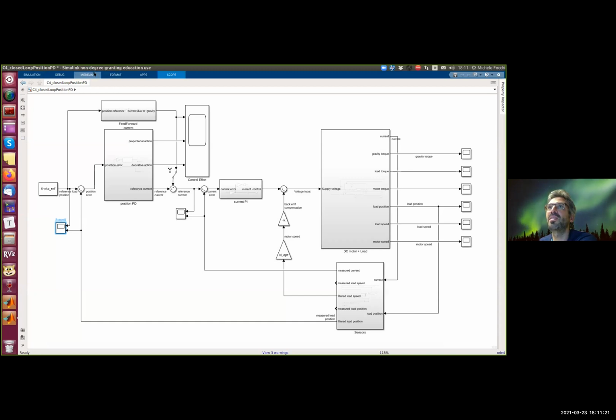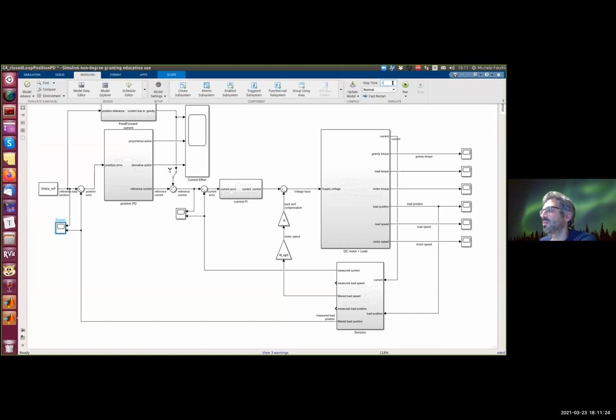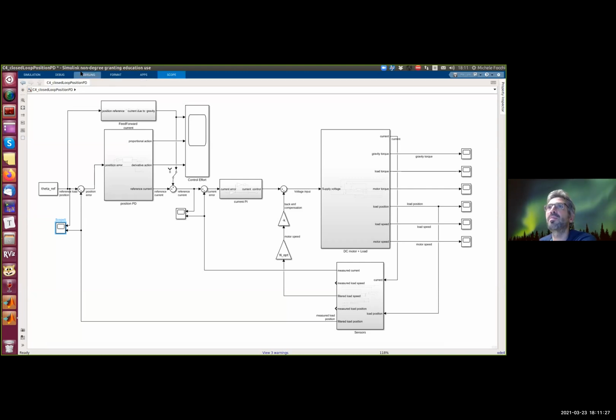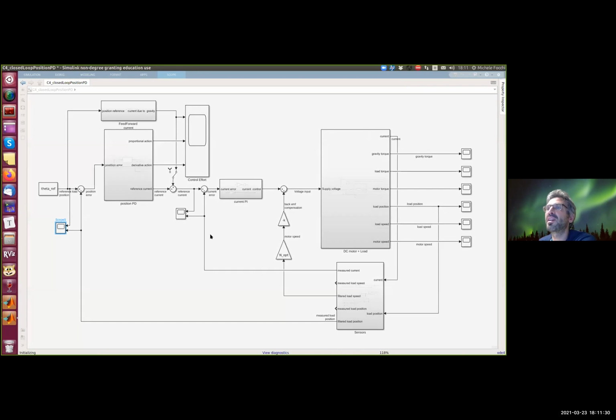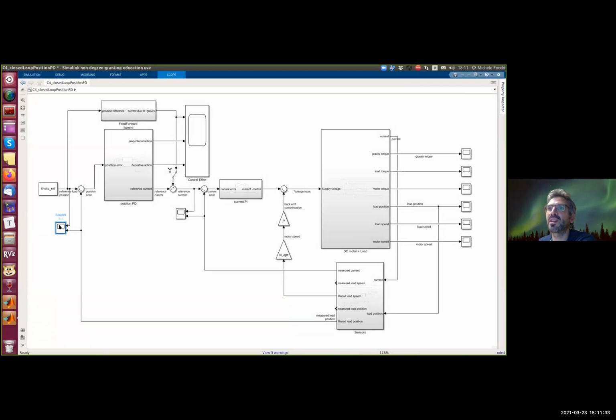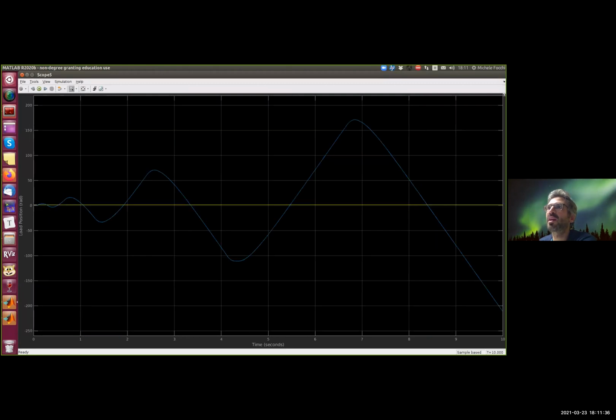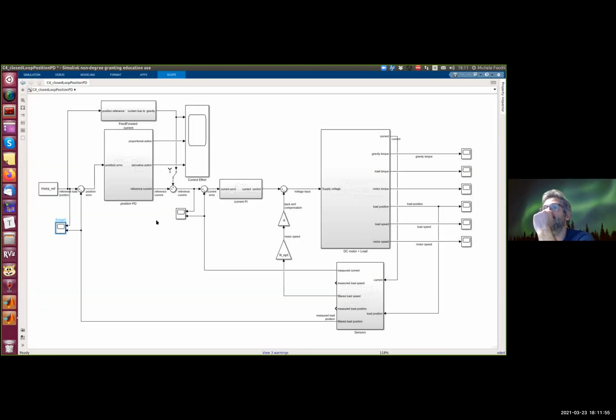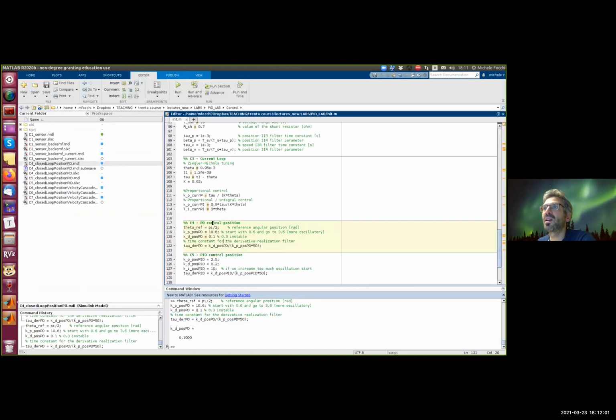You remember the definition of instability? The state diverges from the equilibrium. And if I increase the simulation time to 10 seconds, for example, you will see that it becomes bigger and bigger. And this is very bad. Imagine your robot starting to swing like hell and kicking around people and machines. It's making a mess. So this is exactly what you don't want, instability from your controller. So we need to be careful when we increase the proportional action.